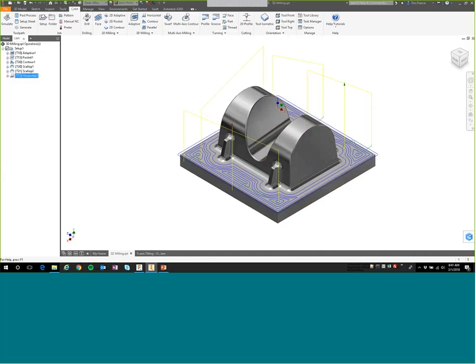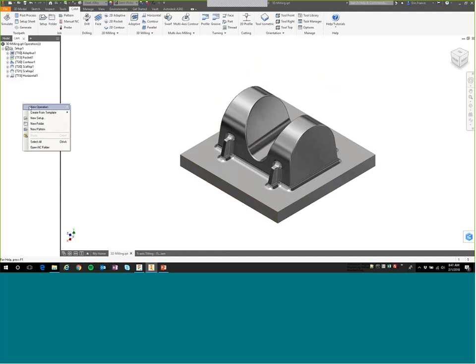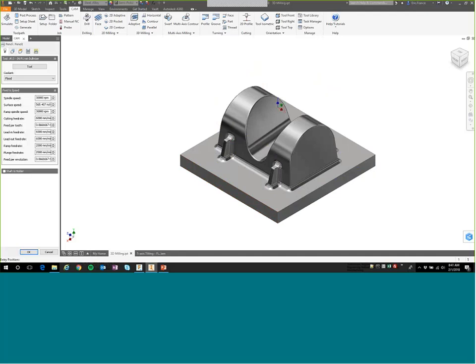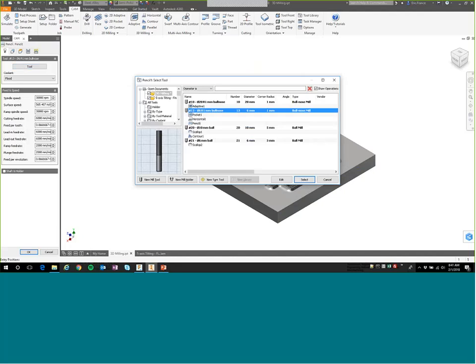All right, so you can see that it's identified the tool paths around that horizontal area, which is good for a cleanup there. And then the last thing we're going to take a look at, we would still have some finishing operations to do on the top, but focusing in on the fillets. So one of our other constrainment tools from a 3D standpoint is pencil. Pencil is going to be focused on just the fillet areas. So we're going to use, not the bull nose in this case, we want to go back to the ball.